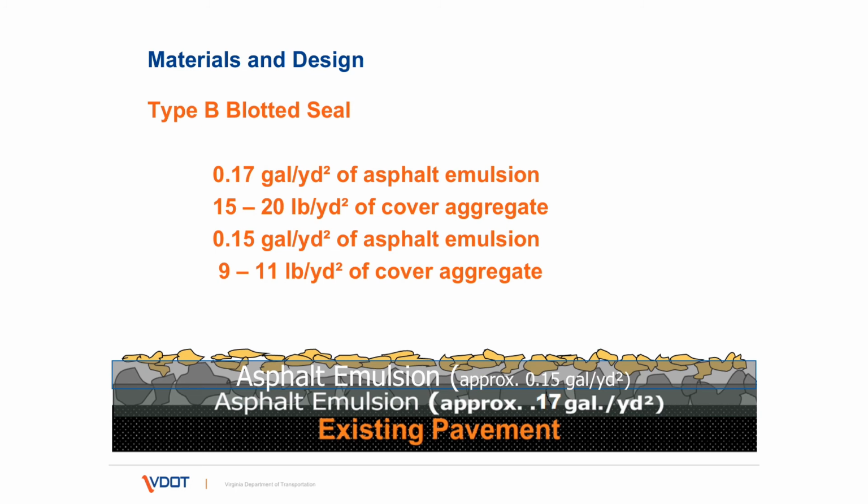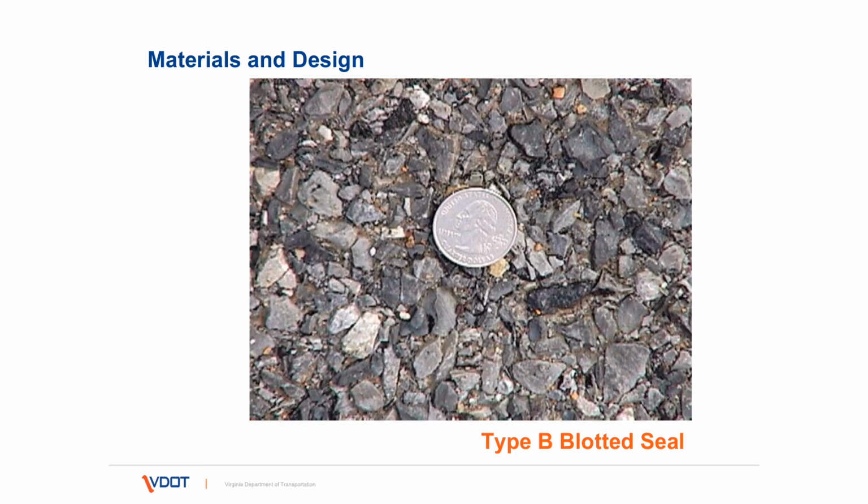What happens there is those sand particles actually lock in those coarse aggregate particles. And we don't have the problem with whip-off of the coarse particles. And here's what that looks like. And you can actually see where those fine particles are in between the coarse aggregates and lock it in place. That's probably a day old in that photograph.